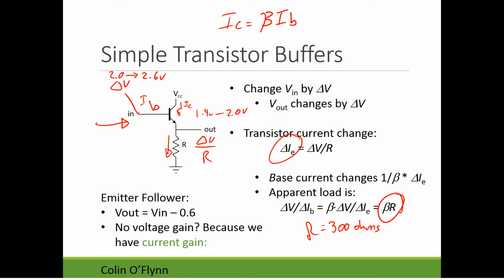You would see this when you're looking at your phototransistors, for example. The phototransistor itself, you often had to have a 1K or larger resistor, and it depends how fast you want the whole thing to respond.